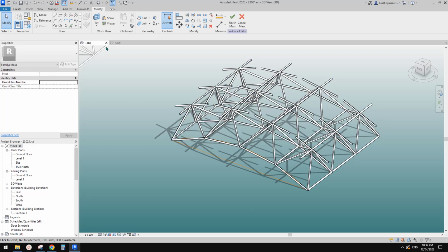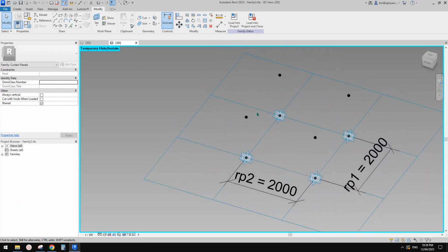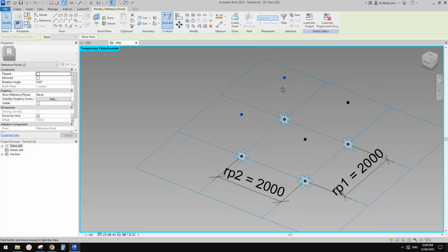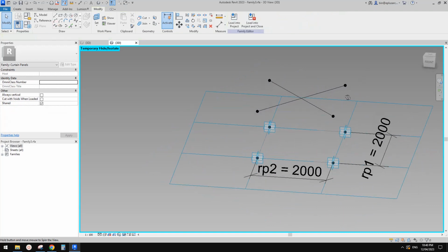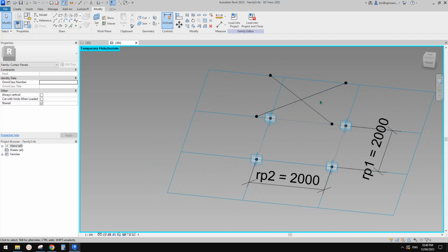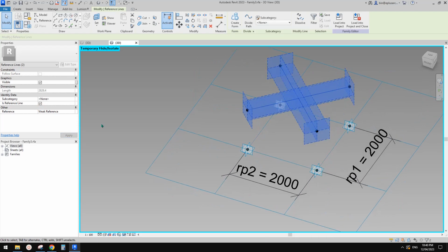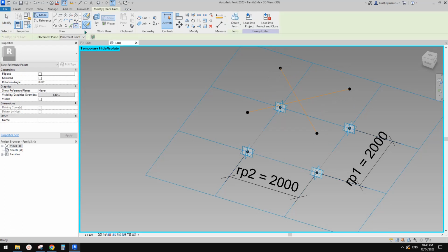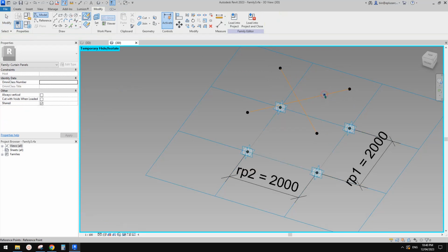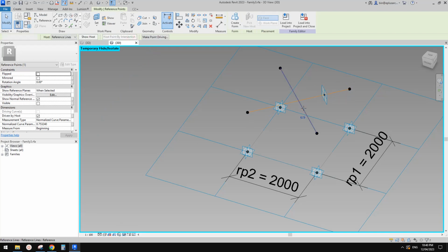Okay, and also let's go back. So I'm going to, maybe we can do this. So maybe if we create these 2 lines, we can get a midpoint, right? But we don't need to see this one, because what we need is this, not this. So maybe, Control Z. Let's just make them reference lines so we can use them, and also we don't want to pick them in that project. So not a reference. So now place a point, use draw on face, place onto this, and then we can just use a host point by intersection, and then we have the midpoint.